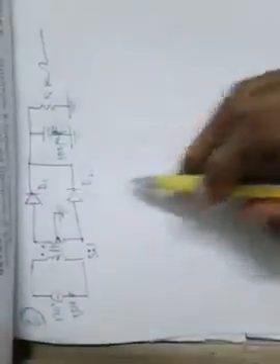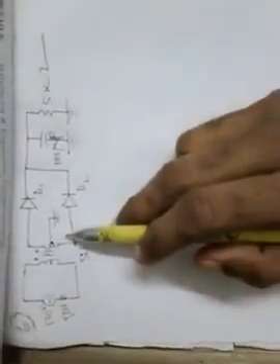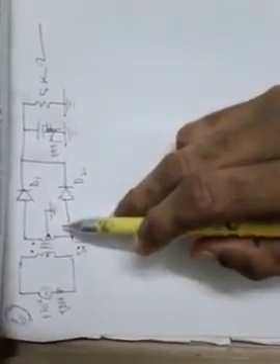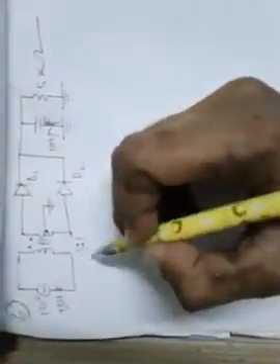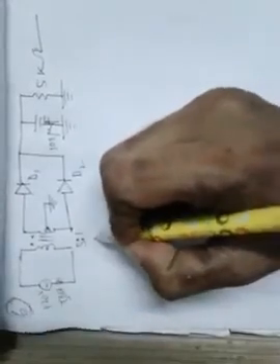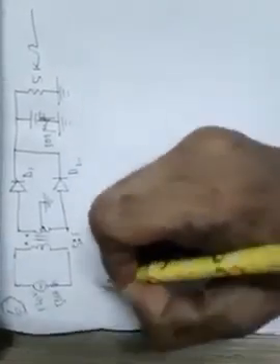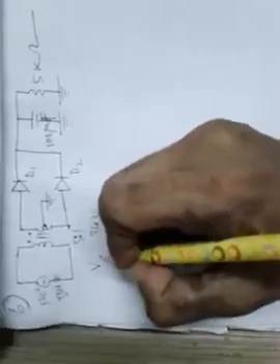Let us look at another problem. Now let us solve the same problem, problem number 6, with a full wave rectifier, that means 2 diodes and a center tap transformer. Since the transformer is a 5:1 step down transformer, like the last problem, the peak secondary voltage will be what we have calculated. It was 34 volt.